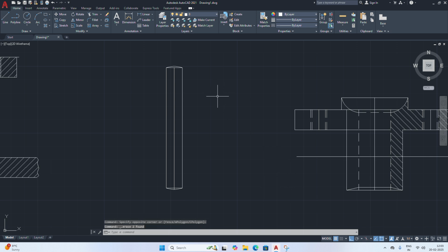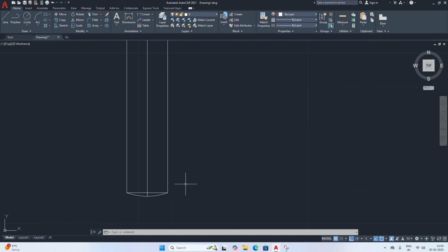Now we'll do one thing. Here we have to offset this line through 15 mm from here. Okay, offset through 15 mm this line upwards, then again that through 3 mm, escape, 2 mm, offset through 2 mm. Okay, now this center line we will offset through 24 mm. Offset through 24 mm. Offset through 24 mm.